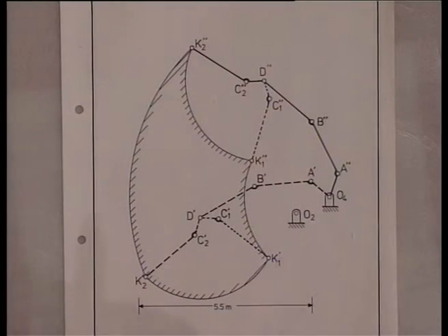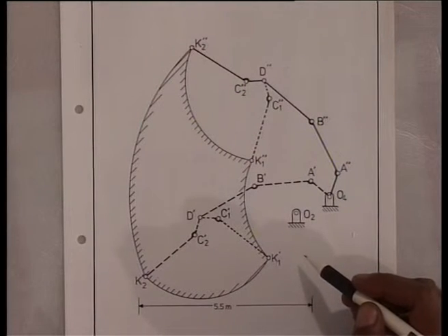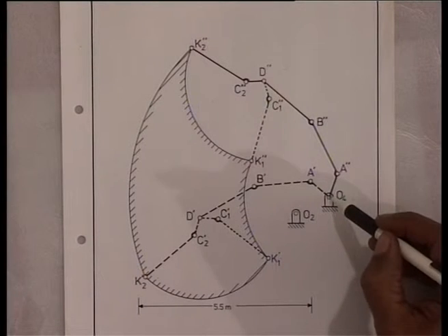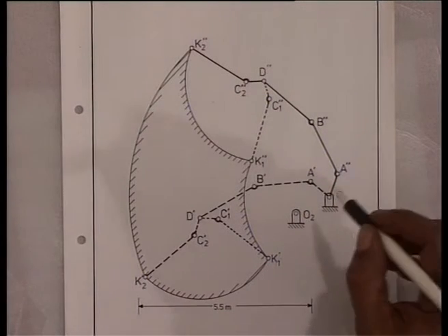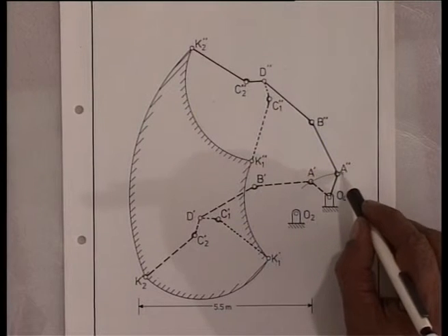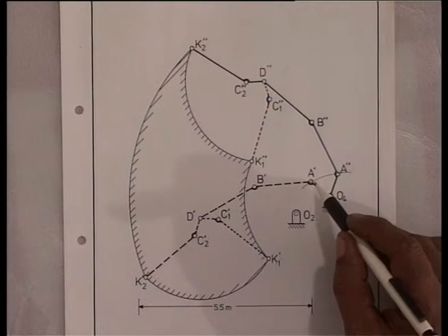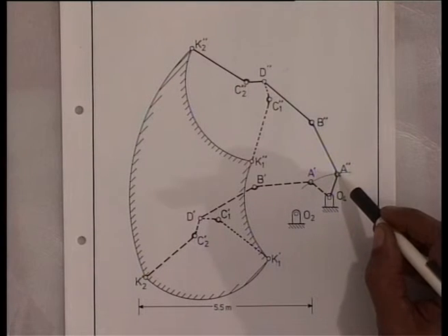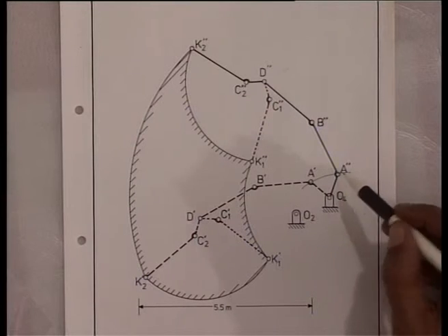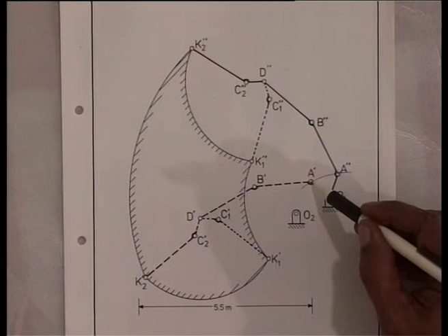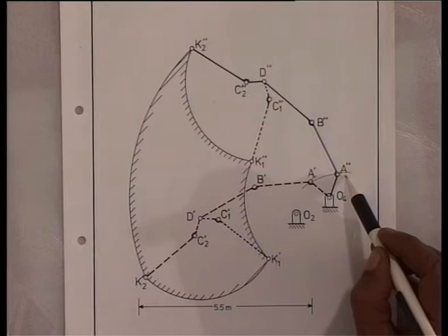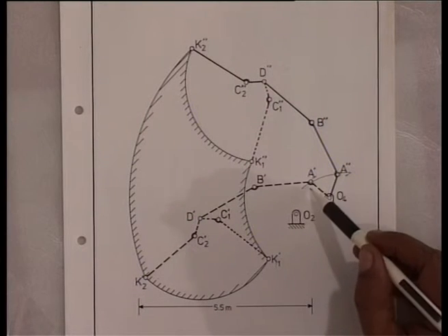If we look carefully at the original diagram, we can see that this distance O4A never changes because they belong to the same rigid body. Consequently, A lies on a circle with O4 as center and O4A as radius. The maximum distance between O2 and A, which is given to us, locates this point. The minimum distance between O2 and A, which is again specified in the problem, locates this point. So, I can locate the position of A for the extreme movements of this actuator Z1.